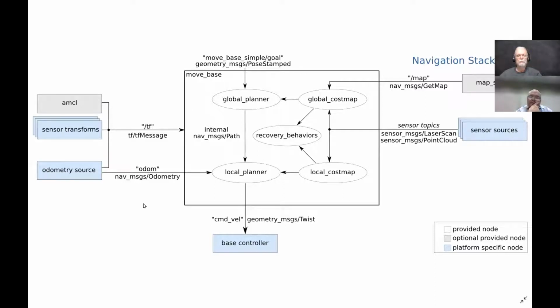The other thing to note is that you're putting this stuff into navigation, so you're getting odometry. If you generate odometry from your wheels, or you have a camera that generates odometry, or you go through the whole process of converting GPS into something usable, that can generate an odometry message. Somewhere you put odometry into your move base node over here. And then AMCL is for when you're running indoors. If you have a laser scanner and a map, it can combine those together and give you updates so you know where you are while you're driving around.